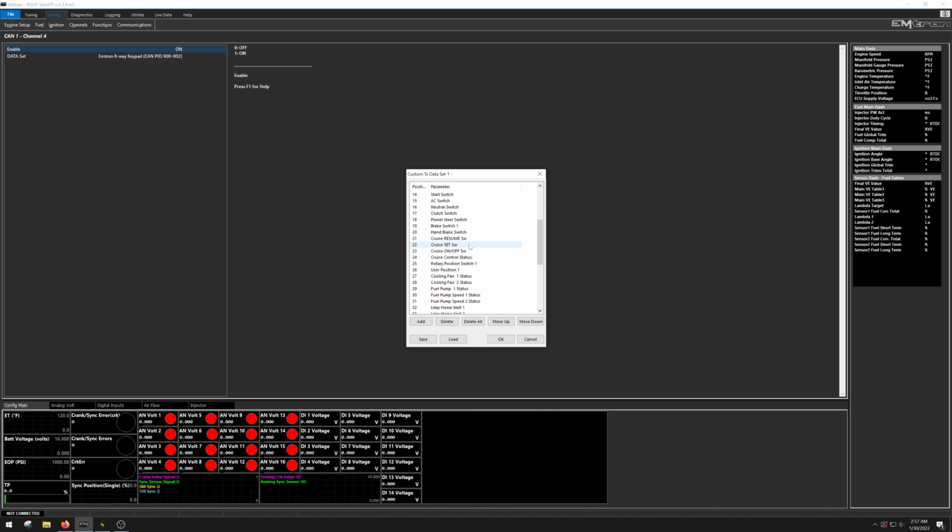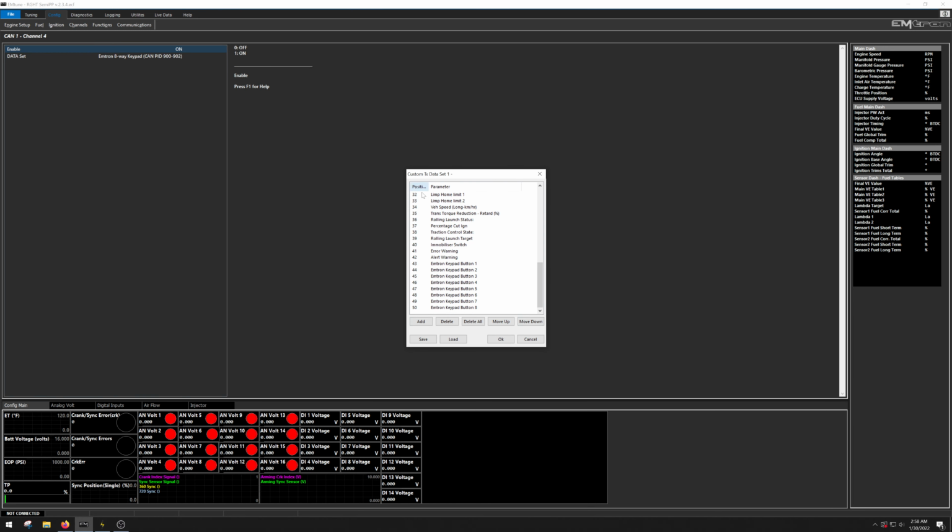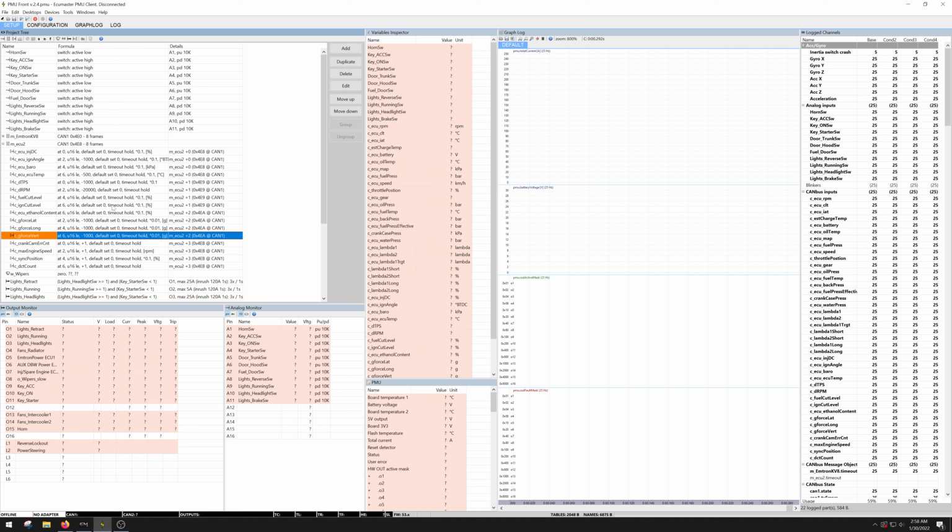all of these can be communicated from the ECU to the PMU. What I'm thinking I can do now is have the PMU function off of these Emtron keypads, because I'm communicating via CANBus to get the values that I want. So let's say, for instance, that I wanted to override the PMU's function for whatever, right? Normally you would need the PMU keypad for that job. But because they're on the same CAN channel, and as long as they're on the correct direction of receiving or transmitting, I could simply click the keypad button. It goes through the ECU, communicates transmitting to the PMU, and then the PMU turns on this value as if I had an ECUMaster keypad.